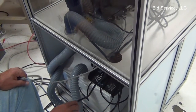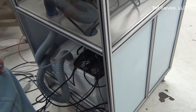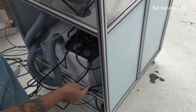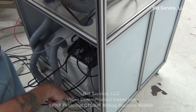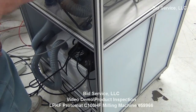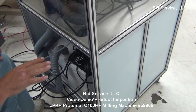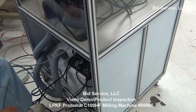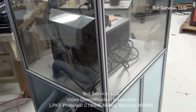The power to the vacuum also is 110, and there's a power strip mounted in the bottom of the cabinet. So all you need is the two outlets and the air supply line. The air supply to this to power the head, because the head is moved by air and motor, is about 80 psi. All the lines and fittings and everything are included with it, and there's also a few boxes of drill bits that'll be coming with it too.